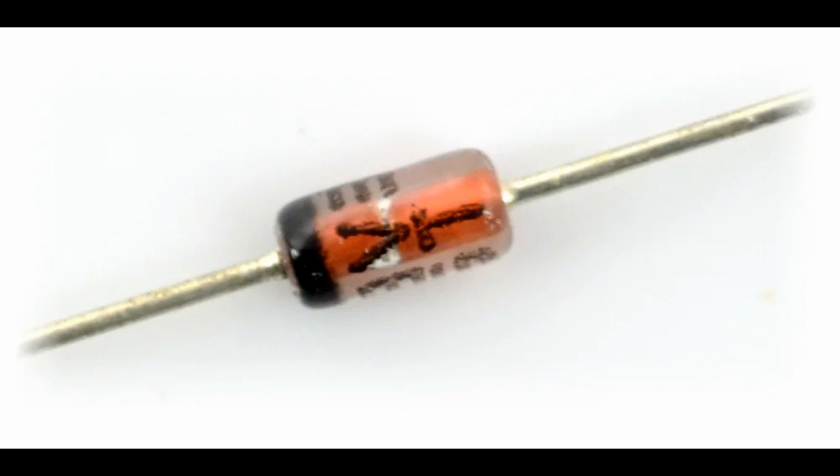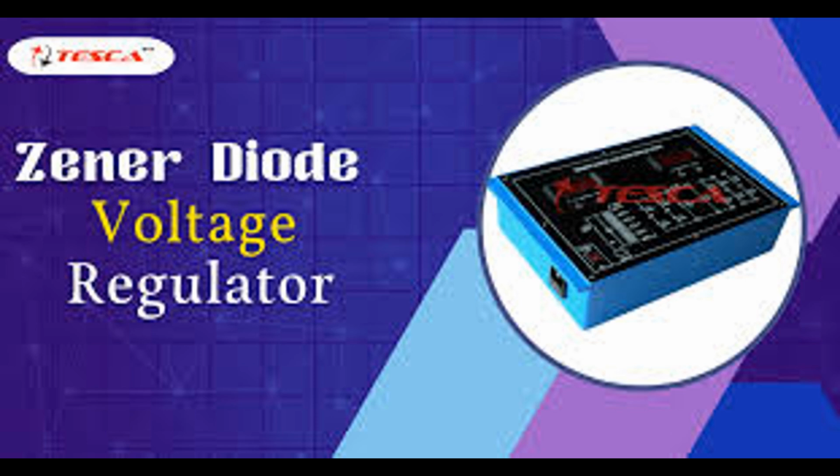4. Dynamic impedance, ZZ. Definition. Dynamic impedance is the small signal AC resistance of the Zener diode in the breakdown region. Impact. Lower dynamic impedance means better voltage regulation. It is defined as the ratio of small changes in voltage and current, respectively.